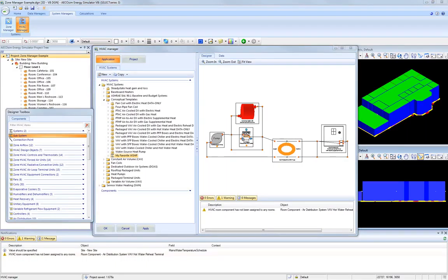To remove this user-defined system from one of the existing subcategories where it is located, right mouse click on the user-defined system name in the tree view, then hover over the Remove from Category selection, then select which subcategory or category to remove the system from.